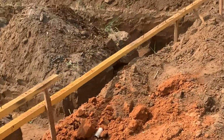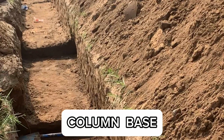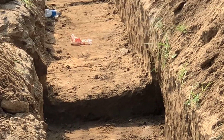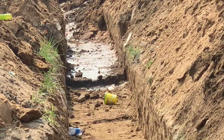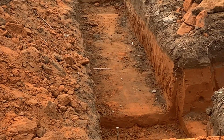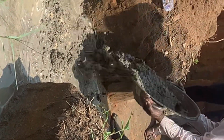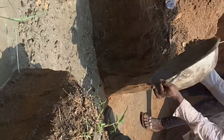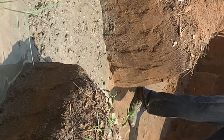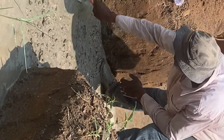Yes. Now, after the trenches have been dug, the column base will be dug as well. So in the process of digging the trenches, they also dig the column base, and after the soil has been excavated and leveled to create a base, the next step is to lay a layer of plain cement concrete, that's the PCC, and it provides a clean level base for the foundation and prevents the penetration of moisture and other contaminants from the soil into the foundation.